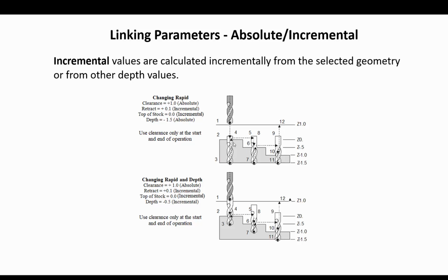After that, it retracts up to the retract plane, which remember is set incremental 100 thou above the top of the stock.